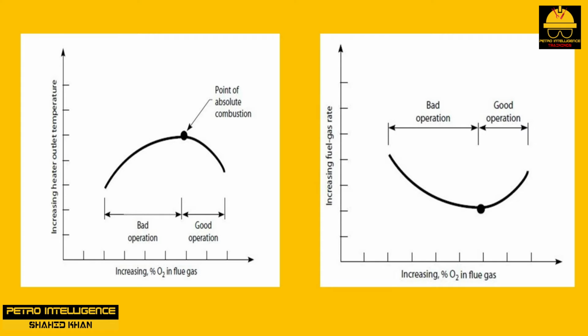Which is cheaper, air or fuel? Of course, the answer is air. Are we trying to make the flue gas to some particular oxygen content specification, or are we trying to save fuel? Certainly, the answer is that we want to get the most heat we can out of every pound of fuel. Well, then, dear viewer, let us neither set nor encourage the use of these stack or flue gas oxygen targets. They are meaningless and often cause more harm than good.